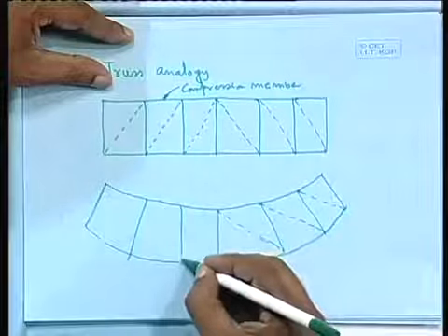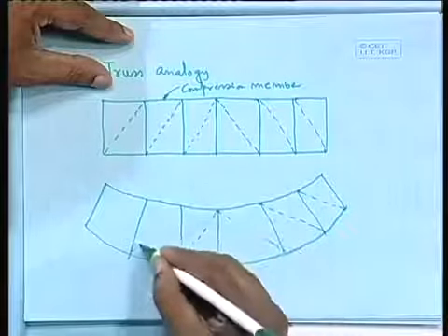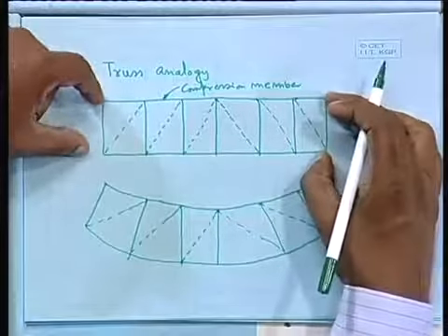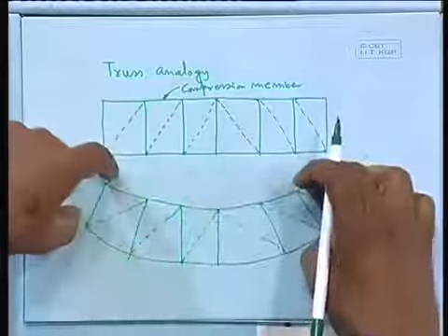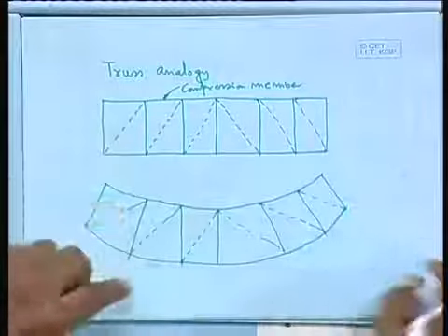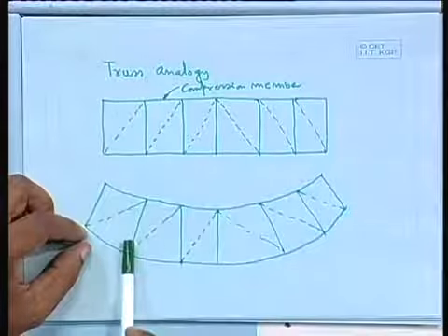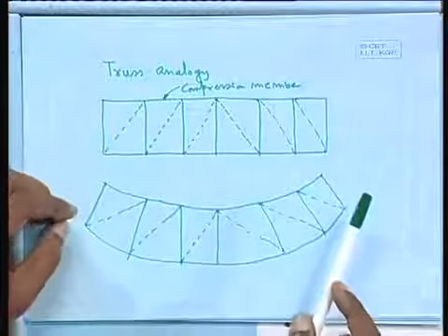You can find out from the deformation, that means as if it is like this. So, that means this truss is deformed in this fashion. What you can find out, the members which are extended, from here you can say, qualitatively, which members are tensile and which members are compression. So, you can find out from this deformation diagram, the members which are extended, obviously, will be tensile members, and the members which are shortened will be compression members.